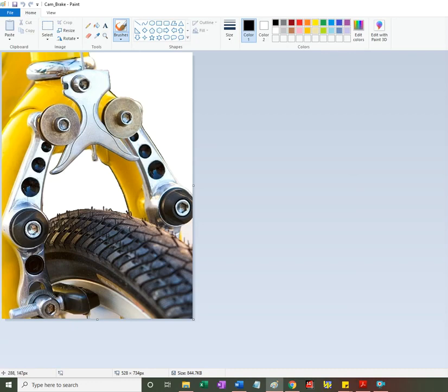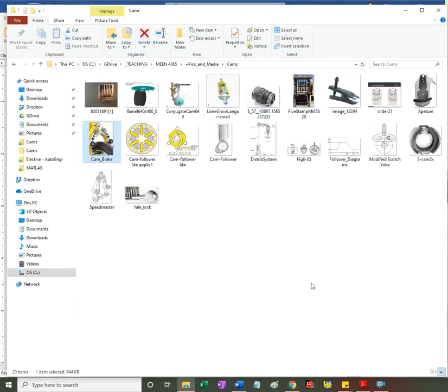This is a wedge cam, we call it. It's guided by the roller, which has two side washers. These are the followers. They pivot about this point, and it's not guided. So one guiding happens between the washers of the roller, and then there's the cable that pushes it. But we can analyze just one side, and we can assume that the cam moves rectilinearly. And again, this is a wedge cam mechanism example.